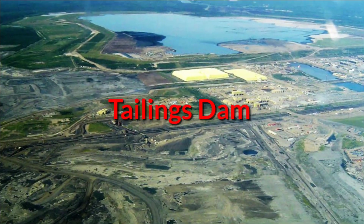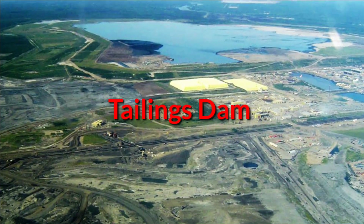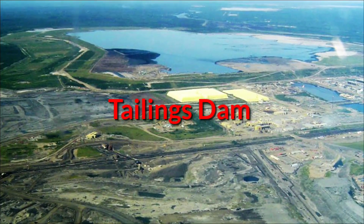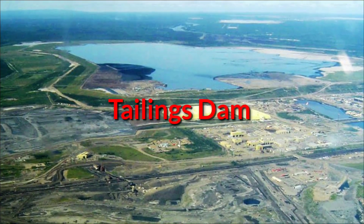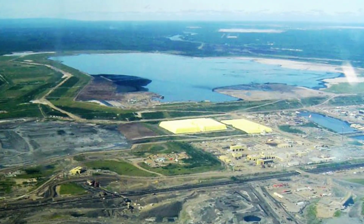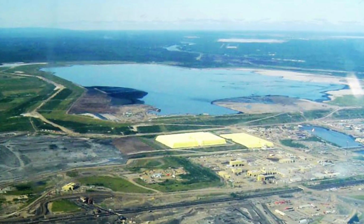Next one is the tailing dam. A tailing dam is typically an earth-fill embankment dam used to store tailings, which are produced during mining operations after separating the valuable fractions from the uneconomic fraction of an ore. Conventionally, water retention dams could serve this purpose, but due to the cost, the tailing dam is more valuable in that area.